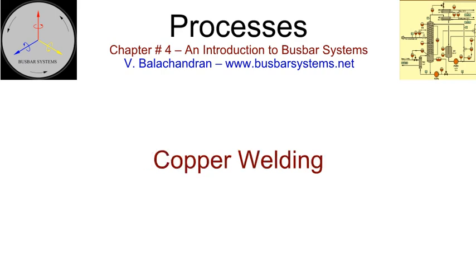Copper welding. Copper welding in the manufacture of busbar systems is now limited to welding tabs to meet the requirements of terminations and orientations. A bolted joint is an alternative solution. However, every bolted joint may require plating, fixings, boots, and accessibility to reach the location, all of which will be far more expensive than welding.